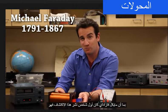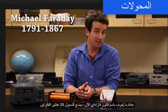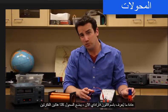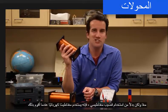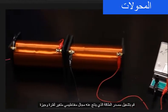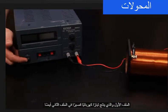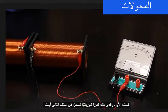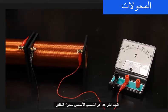Since Michael Faraday was the first person to publish this discovery, it's usually known as Faraday's law. Now, the transformer puts both of these ideas together, but instead of using a bar magnet, it uses an electromagnet. When I turn on the power supply, it briefly produces a changing magnetic field in the first coil, and that produces a brief electric current in the second coil. Also, when I turn the power supply off, again there is a brief current, but in the other direction.